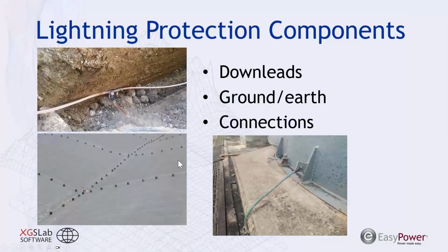Obviously, we're going to have all of our connections too, that are going to be very important to be able to withstand that significant amount of current over that short duration, as well as, from a heating perspective, the thermal limits of that material, as well as the physical limits, because as you have a lightning impulse coming through a connection, it's going to have some significant physical or Lorentz forces that are going to try and force that connection apart from any other metallic structures.